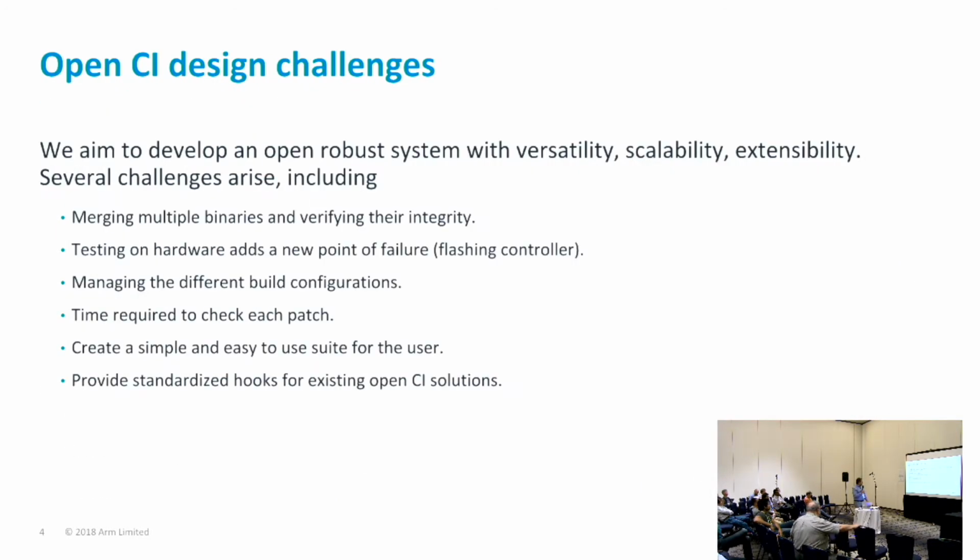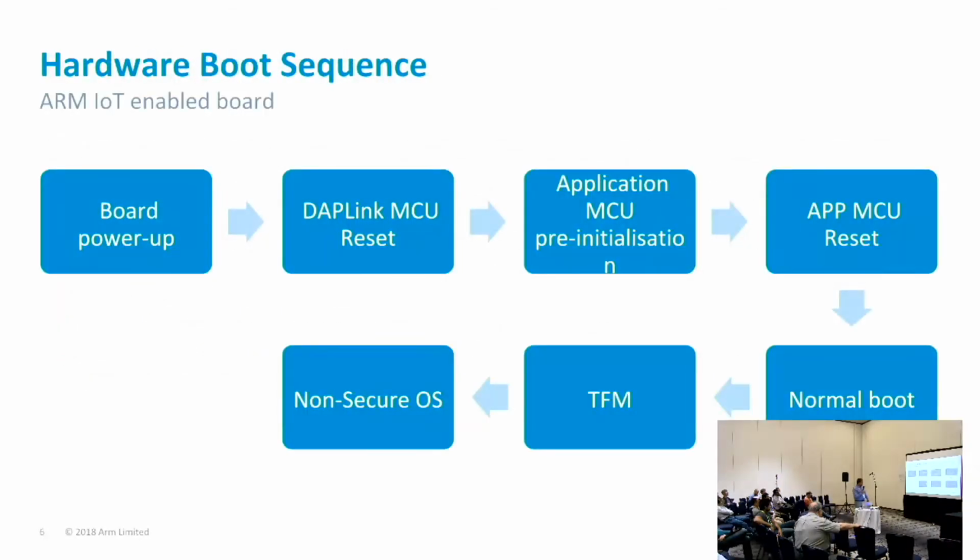Yes, basically when I'm referring to hardware control, I'm mostly referring to the debugging. So I'm referring to a housekeeping interface that will allow you to control the hardware before TFM and before normal boot has been performed. This is a development board, and in most cases, even in a production board, you can use a stage 2 bootloader, which is what we provide as a way to verify the root of trust on the secure side. So if something goes wrong in the bootloader side, the TFM test will fail if you implement something wrong.